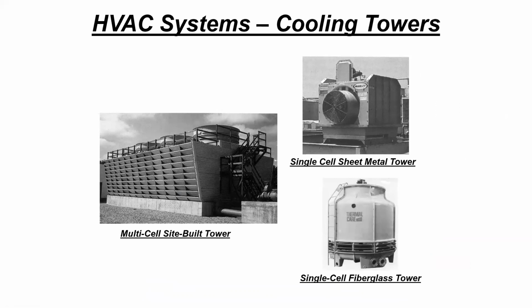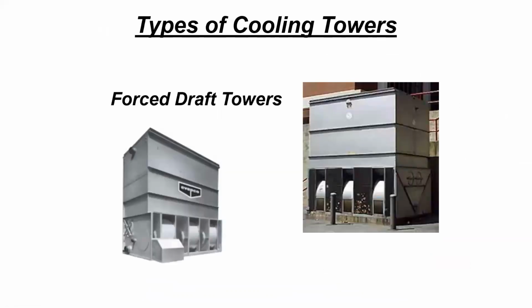Here we have different types of cooling towers. You can have forced draft towers, where on the bottom side we are mostly forcing the air to go through the tower. So the water comes downward, and air is going through the water. There's direct contact between water and air that causes evaporation. That evaporation cools down the remaining water. That's the main principle of cooling water using the cooling tower. But forced draft cooling towers are more limited, they're smaller, and you usually force the air from one side.